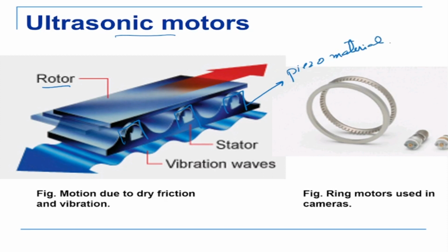Now in this piezo material, if I give it a particular charge, this will expand. The moment it expands, it will tend to push this. So first of all, there is physical contact in here. In a DC motor, the rotor and the stator have no physical contact; there is an air gap. Here, there is physical contact between the rotor and the stator.